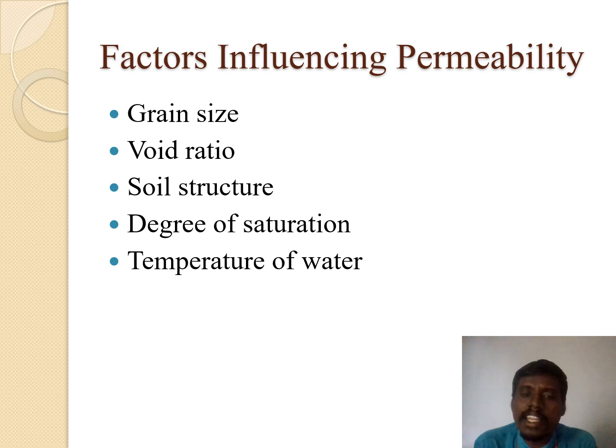The next thing is the degree of saturation, because I clearly noted that Darcy's law is only applicable for saturated soil. For fully saturated soil, that means S value 100%, no more water can be permitted to permeate.